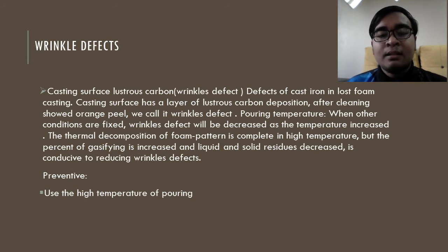The thermal decomposition of the foam pattern is complete at high temperature, which is conducive to reducing wrinkle defect. How do we prevent it? Use a high pouring temperature.